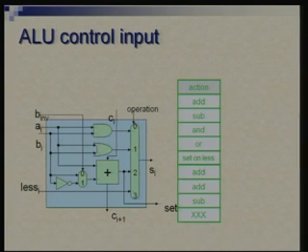So, I am recollecting the ALU design. One bit of the ALU is being shown here, and you would notice that we need 2 bits to control the output multiplexer. It has to select from one of the 4 possibilities, and 1 bit is actually used to invert B if necessary. Whenever you are doing a subtraction operation, B needs to be inverted. So, we need to form 1's complement and give initial carry, so that negative of B comes. So, 3 bits are required.